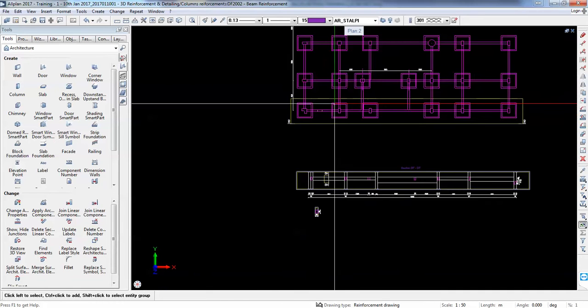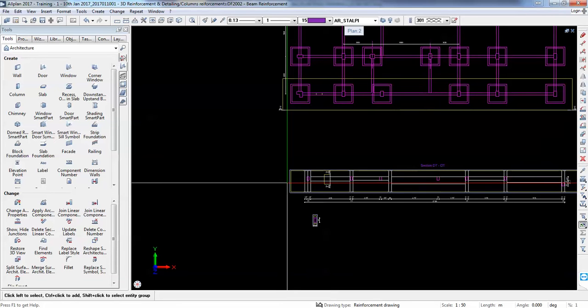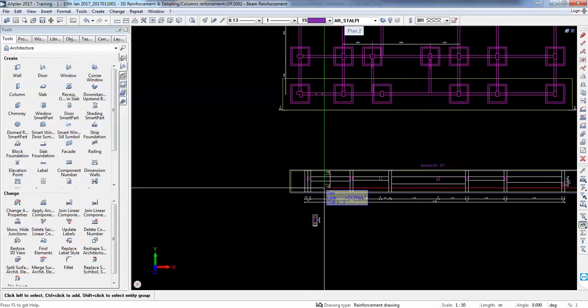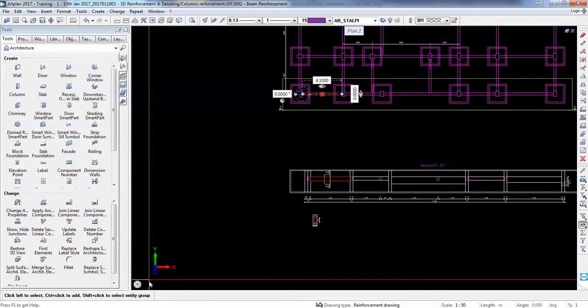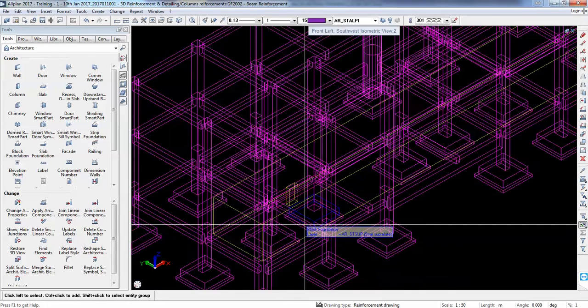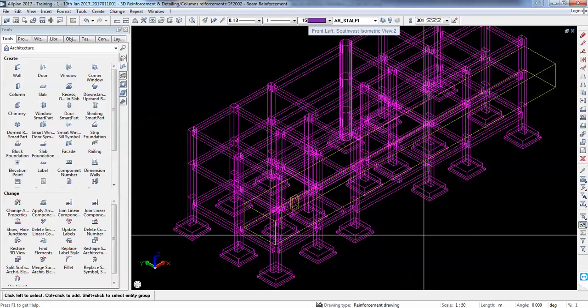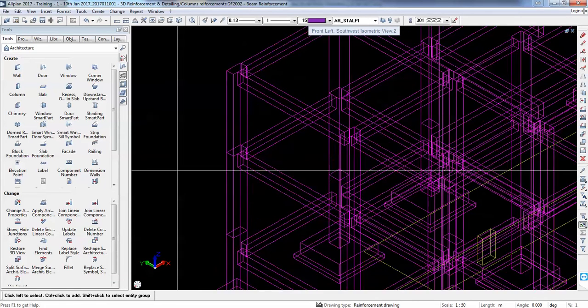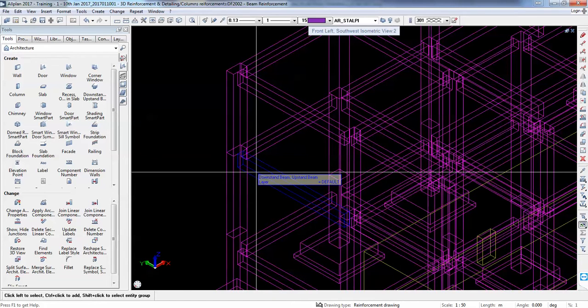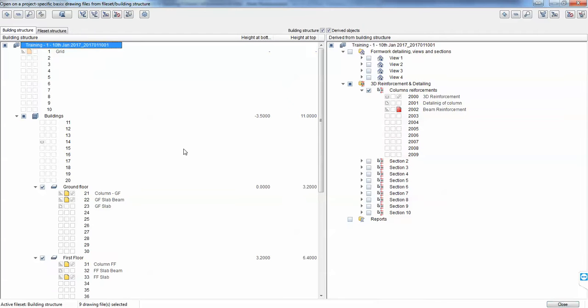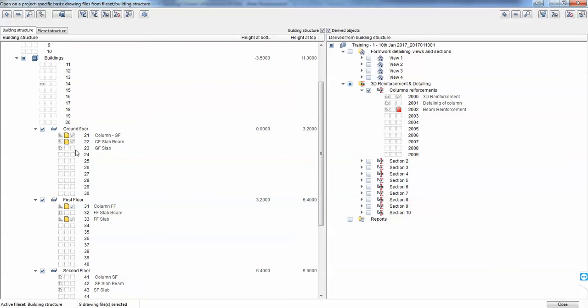Also, in this situation, you do not have a slab. Is it okay if we add the slab? We want to add the slab also. Okay, because it's quite important for my discussion. If I add the slab, I can show you how the materials merge together. So if it's poured concrete and they both have a concrete area, the concrete of the beam and the slab will merge, and we will get continuity of materials. So it will be a good detailing.